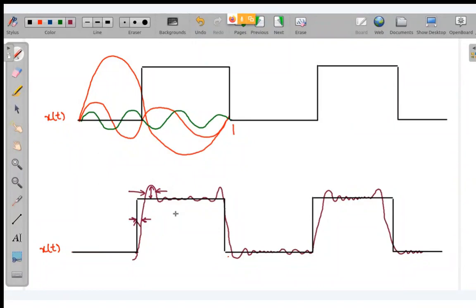Now look, if you have D flip-flop, you cannot construct JK flip-flop using D, unless you have inverters and additional hardware. But with the help of JK flip-flop, without any additional hardware, you can implement all other flip-flops. So that is why JK flip-flop is the universal flip-flop that we have.